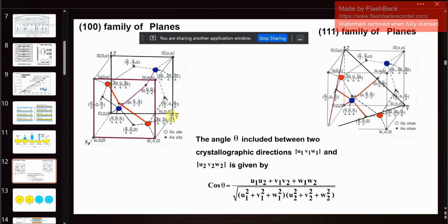So again, as I said, if it has anisotropic, it will be a problem. To understand that, we need to first understand how the silicon's crystal structure actually is. Basically, it has a very closely packed structure which has 8 atoms in one unit cell. So it has two families of planes. It has the 110 family of planes, and it has the 111 family of planes.